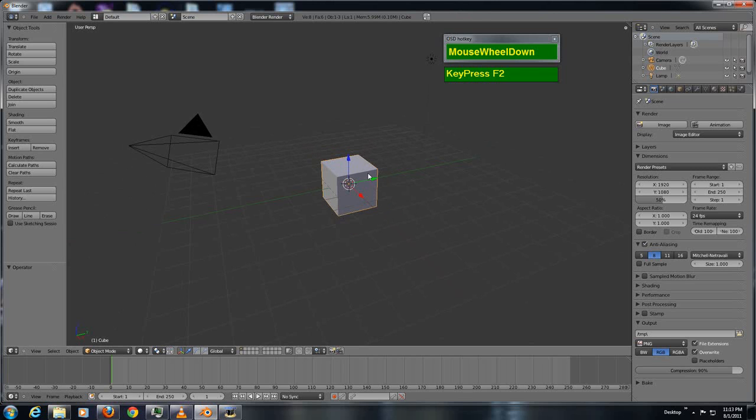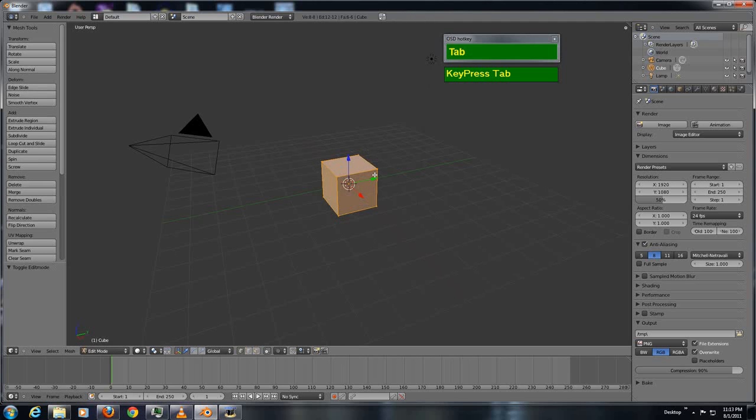So first of all, we need to go to the edit mode. So make sure this cube is selected by right mouse clicking on it, and then pressing the tab key will go to the edit mode. When you're in the edit mode, you will be able to access the subcomponents of a mesh object. So most polygonal meshes are made out of three components.